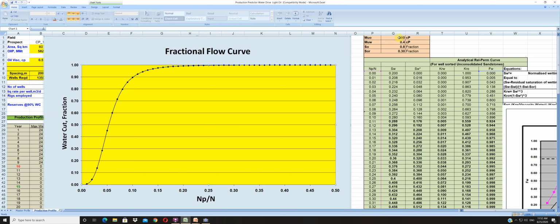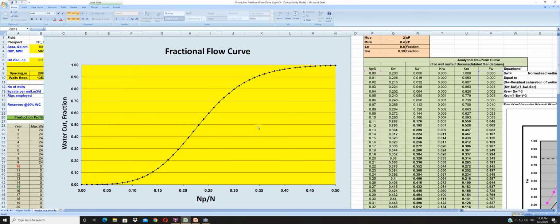So some operators, like me, don't be biased like me, but sometimes I have been in some other place and straight away implemented steam injection to reduce the viscosity of oil and get a significant amount of incremental oil through steam injection, shifting the fractional flow curve to the right. And that's substantial, from 7 to around 35% at 90% water cut.